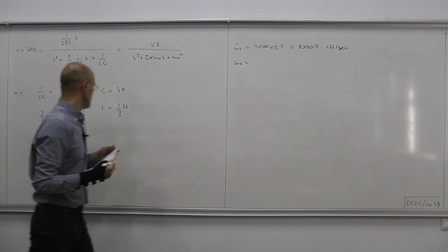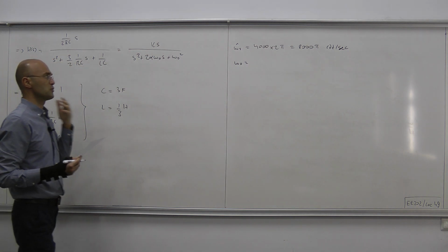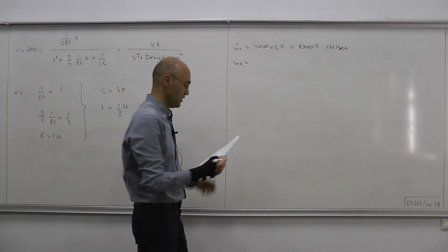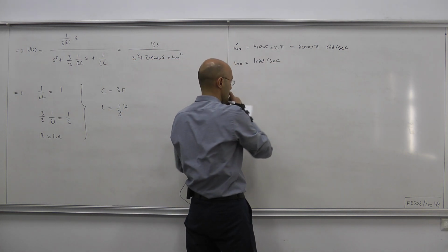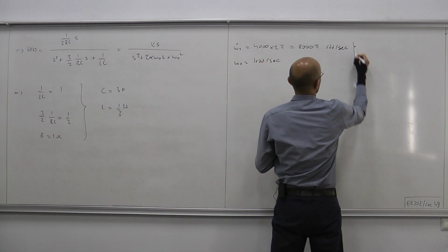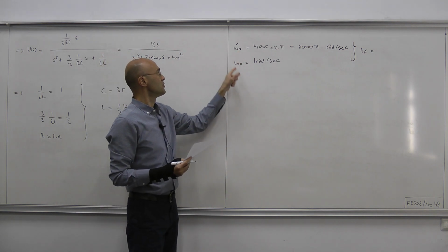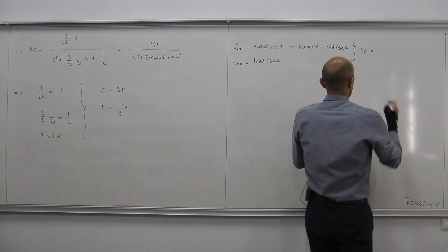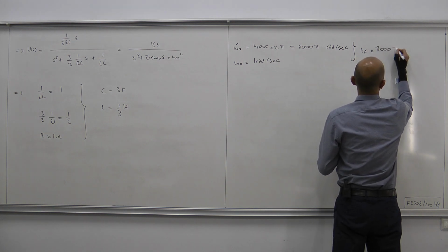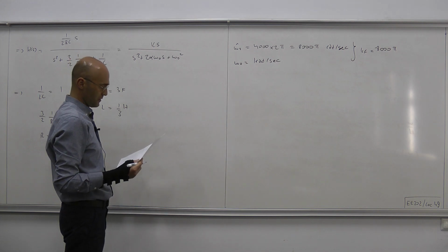And omega 0 was initially 1 radian per second. Therefore, the frequency scaling factor is the ratio omega 0 hat to omega 0, which is 8,000 pi. So that's our frequency scaling factor.